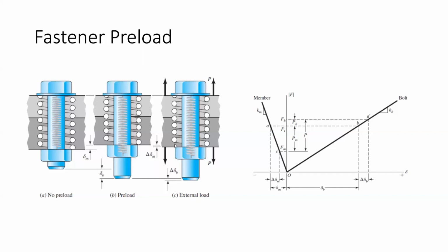And so the fastener is always elongating when you fasten it, and the material is always compressing. So that combined action and the stiffness differential is what causes the bottom threads to be loaded more. So the way that you calculate that tear out strength, as they typically call it, is by viewing these two surfaces as cylinders. So you have one cylinder within another, and you're basically pulling up on this as you preload it, right? And the strength of your system is the shear strength between those two interfaces.